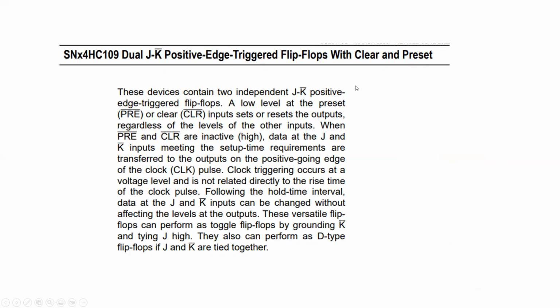I just got this part from the data sheet anyway, okay? So as I told you, when you see bar this way, it means it's active low. So if you want to clear, you have to input 0, okay? So they are inactive when they are high.